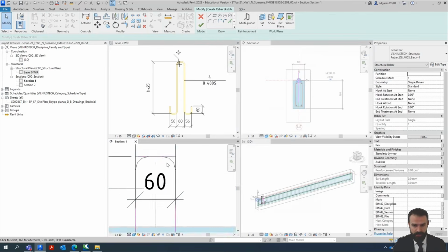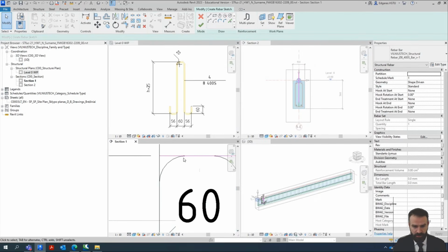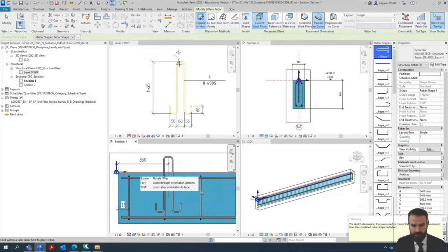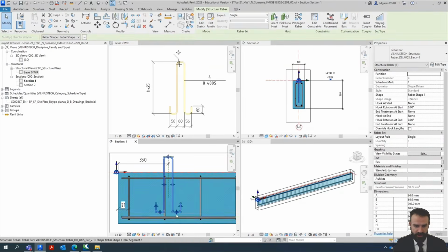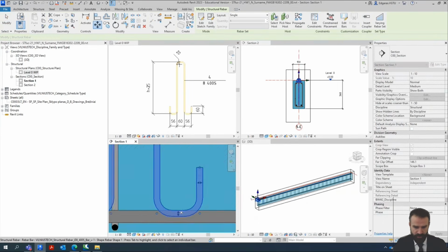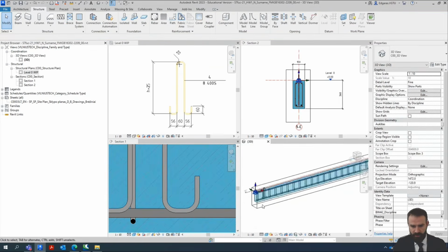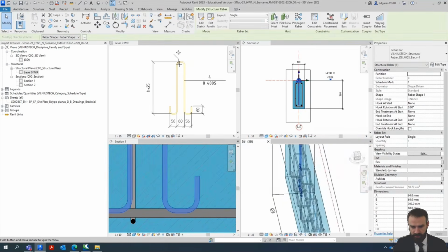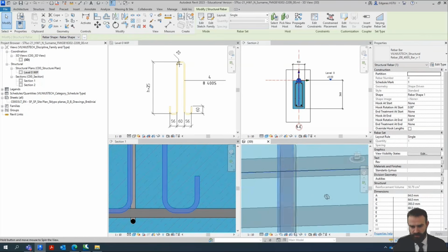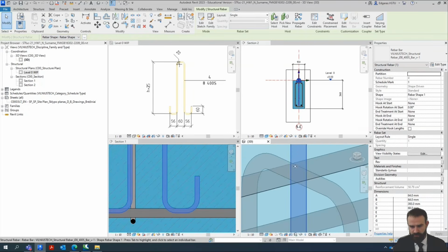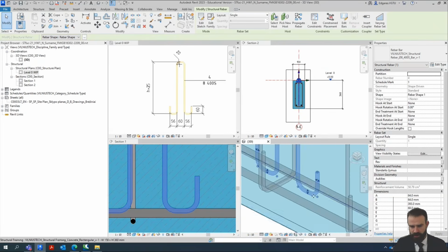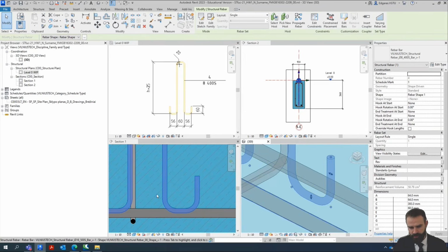And now I can see some black lines here. So this line shows what the bending is okay. It suits the requirements. I can click, and now my rebar is created. Now I need to move the rebar hook down to this position. And if I look in 3D, so now my rebar is located here, and I have some issues. So my rebar is collisioning the transfer reinforcement, and also I can easily lift the bar, and I need some special connection here.